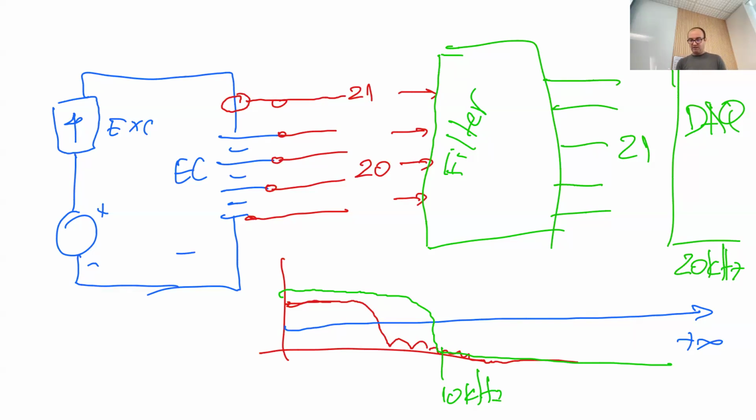And yesterday we realized that we made a mistake when designing these filters. Due to either miscommunication or misunderstanding on my side, we delivered filters here that go up to 10 kilohertz. It turned out that we would like to have impedances much higher than this, so we have to redesign this part. It's not mission critical. We can start the experiments now, but the EIS curves will be limited to 10 kilohertz.